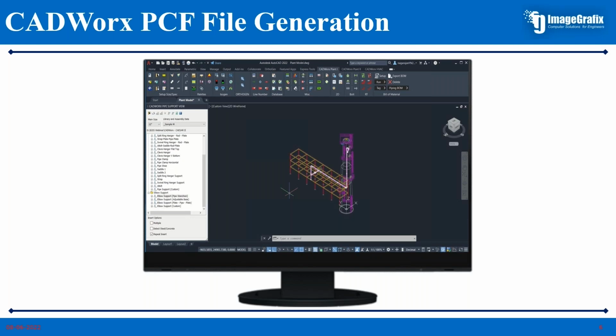along with your pipe support data, pipe model data and everything, you can even transfer your process data also, like your temperature, pressure, design pressure, operating pressure, or any other temperature and pressures which you want to take along with your details. That can also be transferred along with your PCF file. Here we'll look into it in detail.